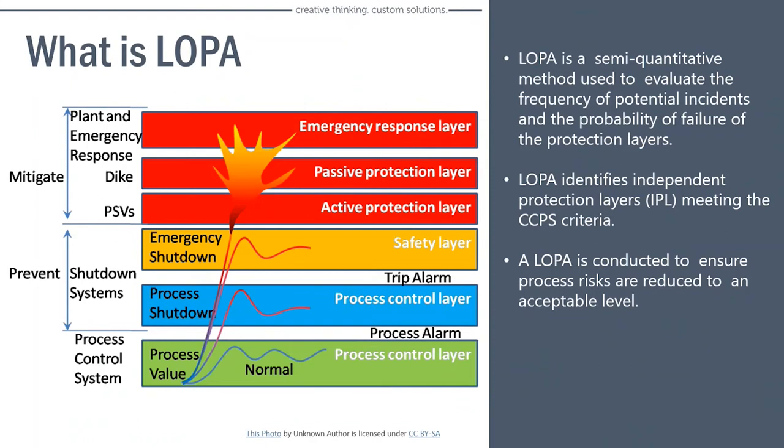If any of you have ever been in a PHA before, you know that it's usually a group of people with extensive knowledge and experience sitting around the table and talking about the severity and the likelihood of certain outcomes from various processes. A lot of times it's a qualitative judgment. Well, LOPA adds a little bit more quantification to that judgment, and it's a way to really look at what safeguards you have in place and how reliable they are.